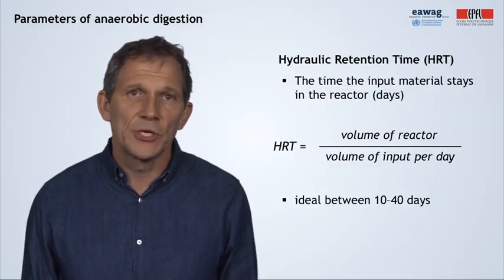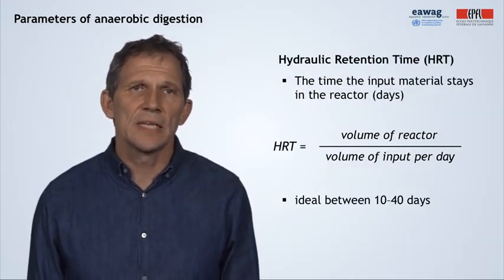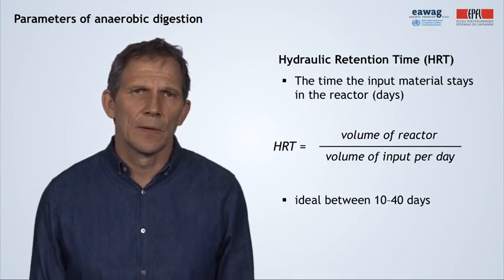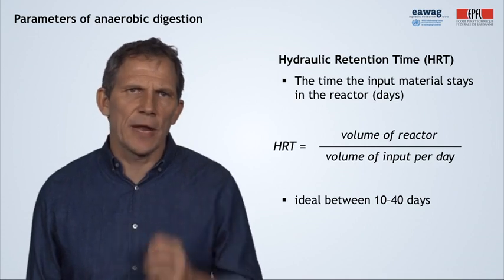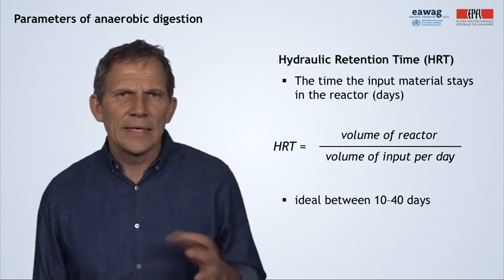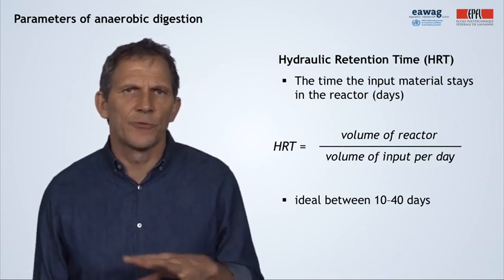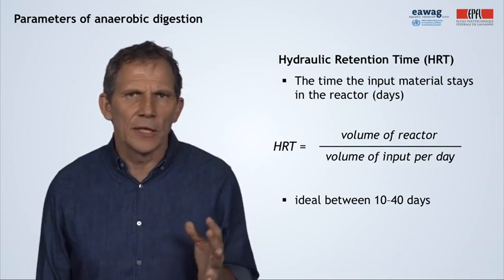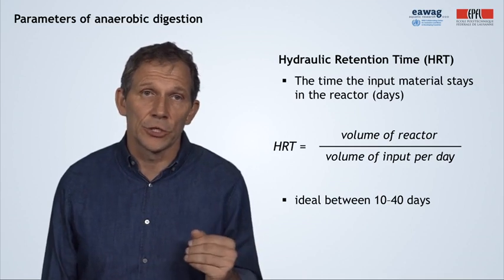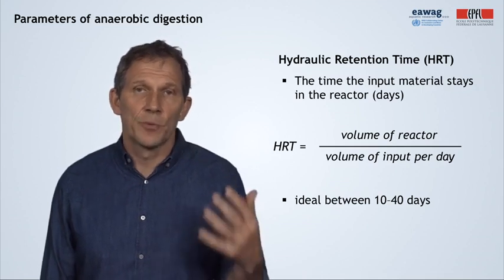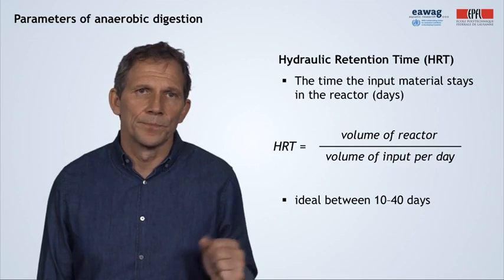A further parameter that influences the process is hydraulic retention time. That is the amount of time that the material stays in the reactor. Ideal is a time between 10 and 40 days. The lower value is rather for higher temperature in the thermophilic range, because the process is quicker.